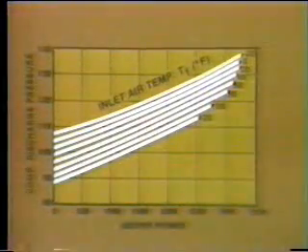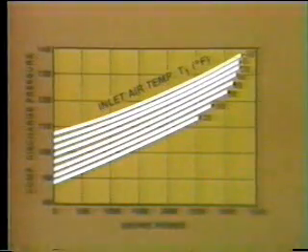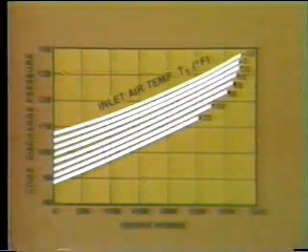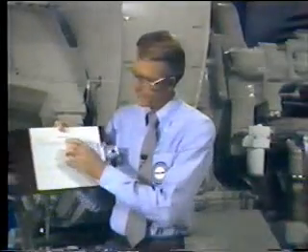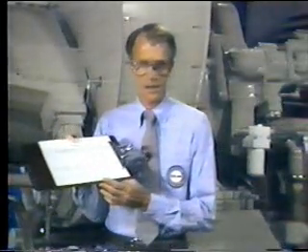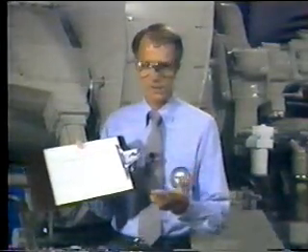You may recall the charts from an earlier lesson that compared PCD with load and inlet air temperature. These charts, along with your PCD log, can help you determine when the compressor needs to be cleaned. Operating personnel should keep a log of PCD indications from day to day, comparing one day's figures with those from another day under similar conditions, which will indicate deterioration of engine performance.